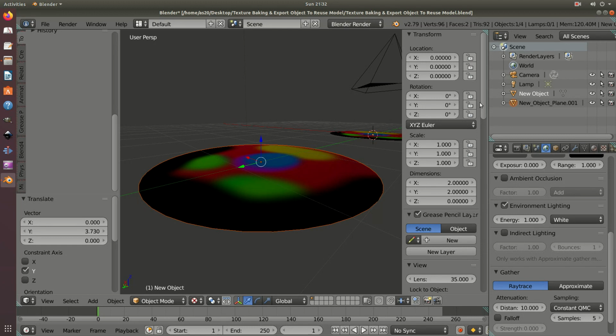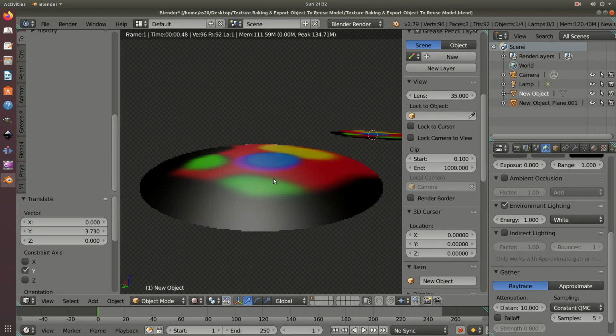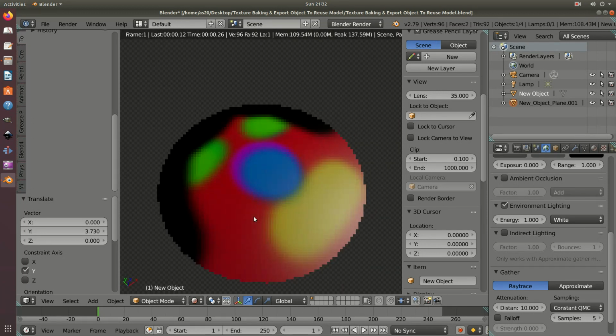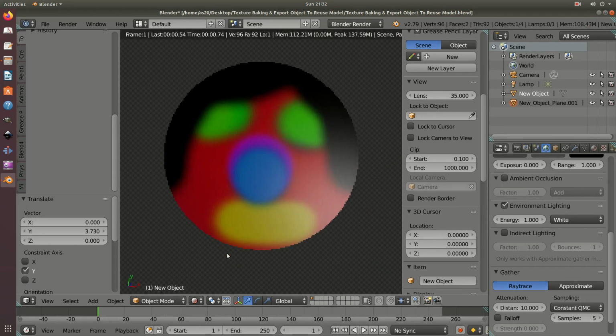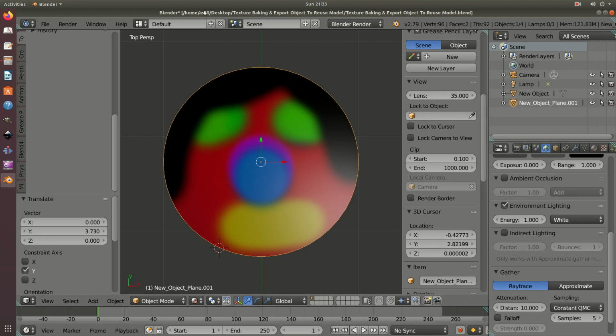To see a nicer look, I am just going to world tab, property tab, and checking this environment lighting on, as well as going to render mode and going to the top view, material mode, going to the top perspective and pressing 5 to take it orthographical mode.